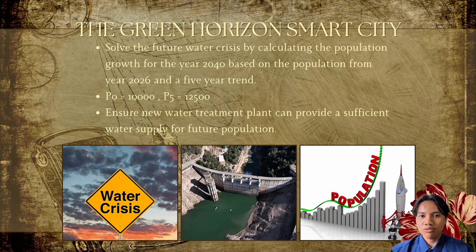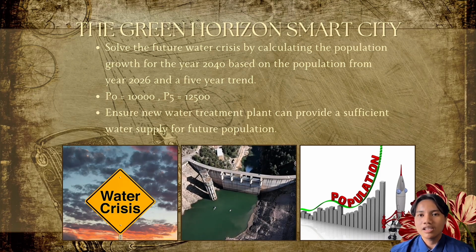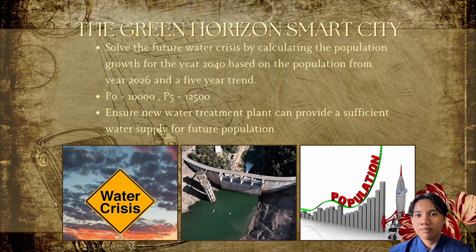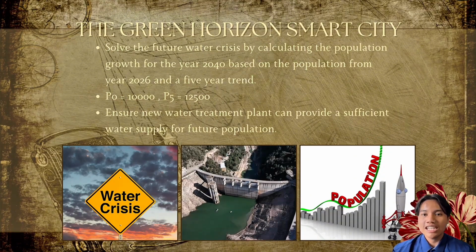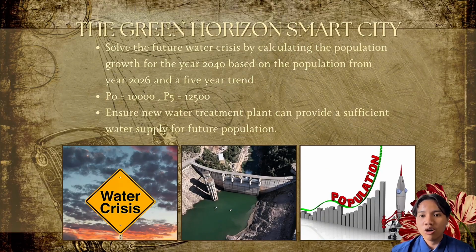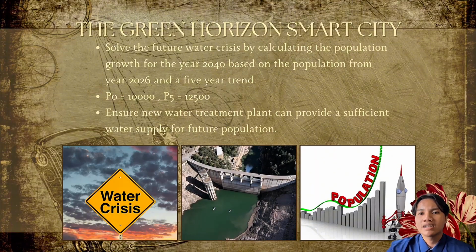Therefore, we also need to calculate the total daily water demand in megaliter per day (MLD) to ensure whether a supply of 150 liters per person per day is sufficient for the long-term operation of water treatment plant.